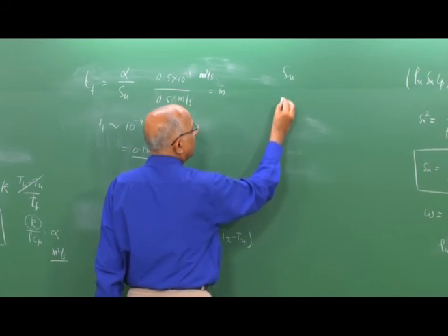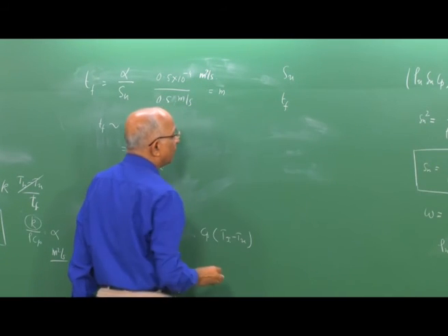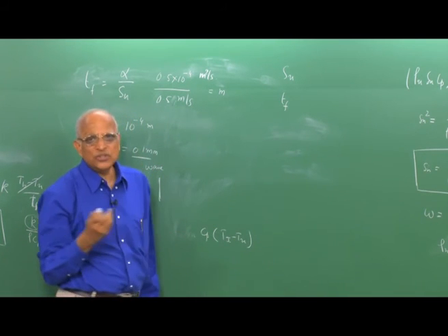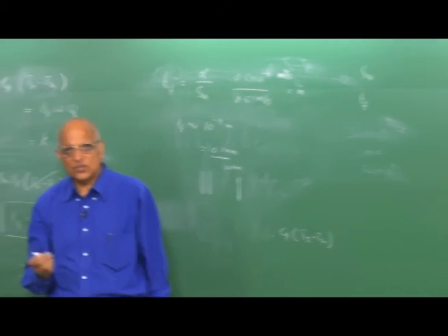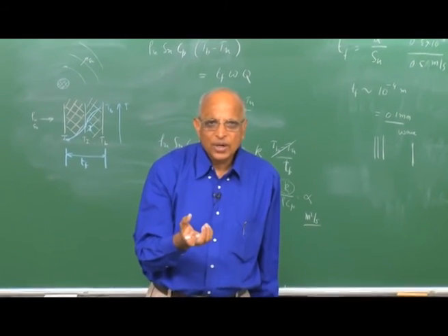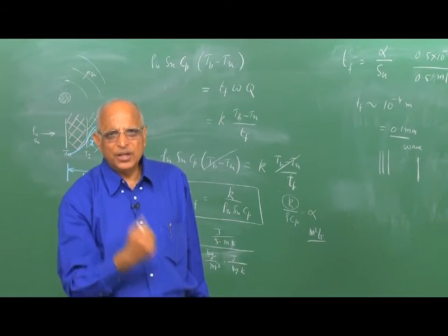We also derived an expression for the flame thickness TF. I would like to use these two to find out how much energy, if I do not use the lumped mass system, but if I am interested in having a kernel of a given size, is required to ignite it.